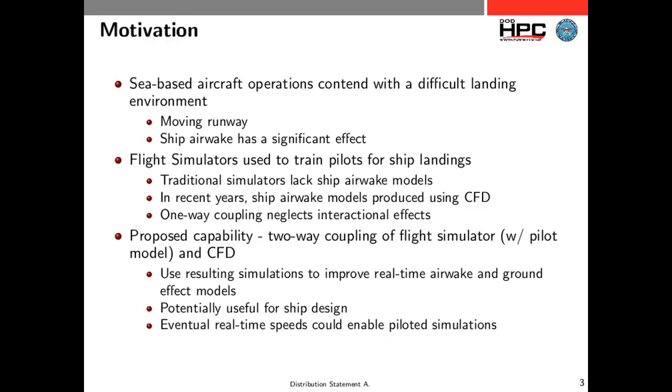But the problem with that is that it neglects any sort of interaction between the aircraft and the airwake, especially when you talk about rotorcraft coming into ground plane effects, but instead of a flat ground plane, you've got a ship. There can be significant interaction effects. So what we proposed to do was two-way coupling of the flight simulator and CFD, in this case of a rotorcraft, and they're moving on to fixed-wing aircraft now.